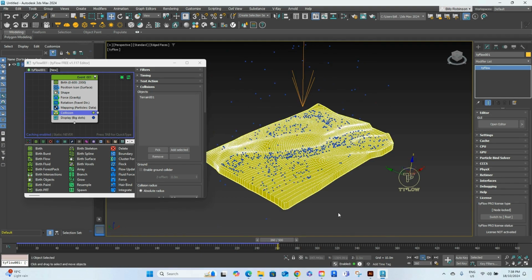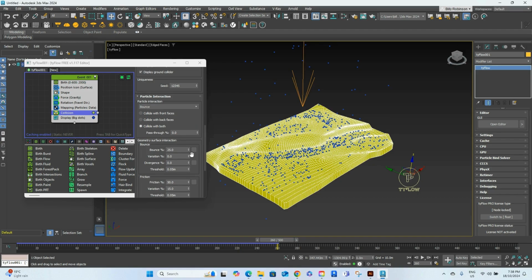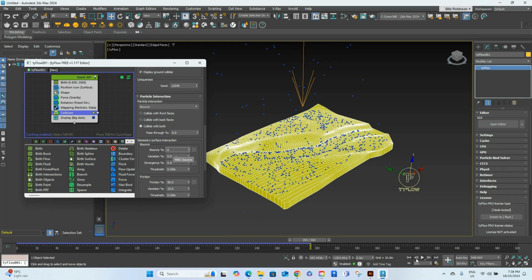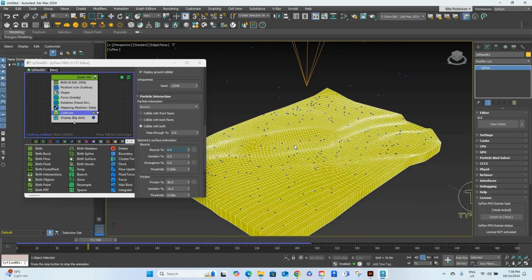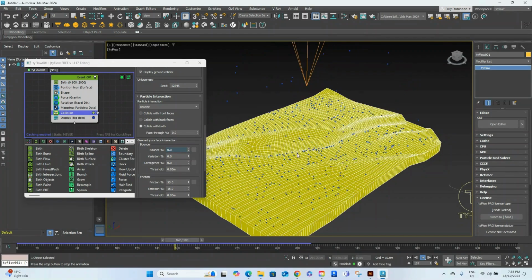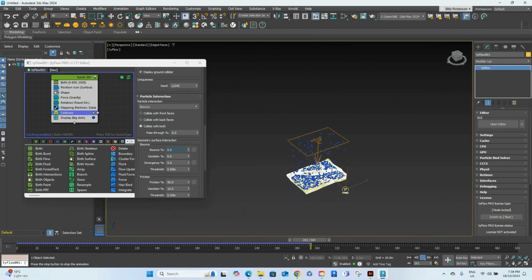Another thing to mention in collision, I believe, the particles hitting the landscape are bouncing up. So that's not going to happen. So we'll set that to 0, enter. And now we can start over, and now we should see the sliding down and the build up of particles. So this is an example of using Tyflow for a flood simulation.